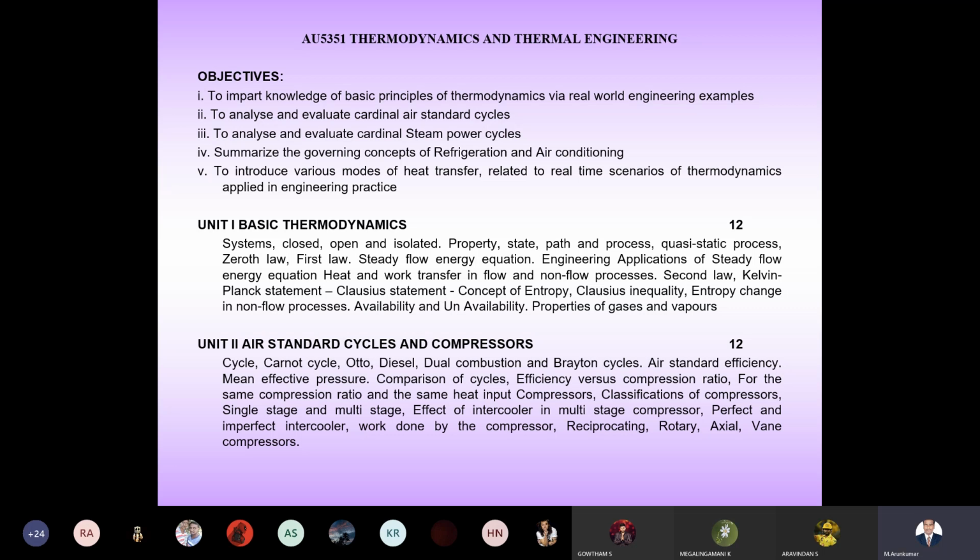Right? So we can have the W equation. W adiabatic is equal to 1 by 1 minus gamma into (P_F V_F minus P_I V_I). Just go through the derivation. That was an easy one only. You just have to substitute the values and integrate. Then we can get the value for W adiabatic, that is 1 by 1 minus gamma, P final V final minus P initial V initial.